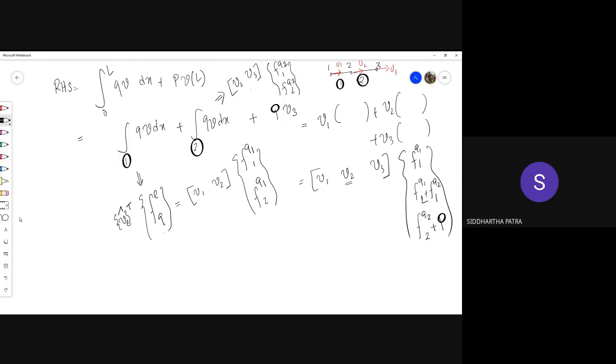And if we were to work with 2D elements, or beam elements where we would encounter more than 1 degree of freedom, that addition would happen not just at a given value. There would be multiple locations where that addition happens. So in the end, if this is our v hat global transpose, we have this expression. So this is our global force vector.